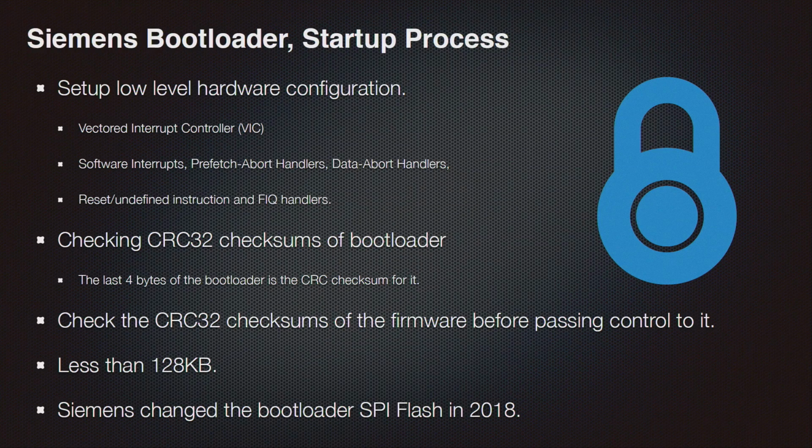All right. First of all, let's look at what the bootloader does in its startup process. It's kind of what you would expect it to do. The bootloader basically wants to get the hardware ready for the second stage payload to be executed. And here we see that, for example, the vector interrupt controller is set up, different hardware parts, but it also checks the integrity of the bootloader code itself and also the firmware.